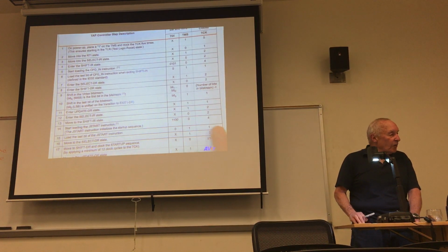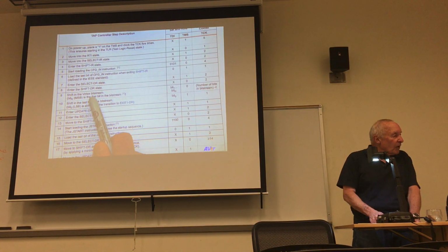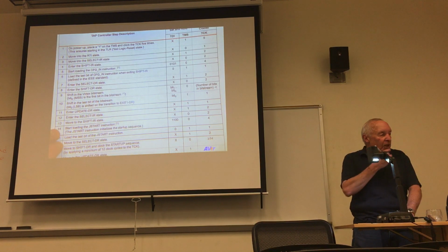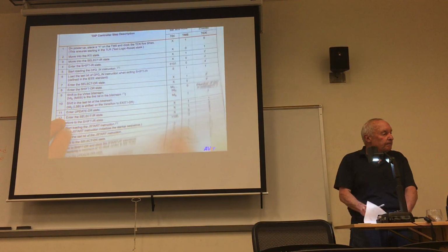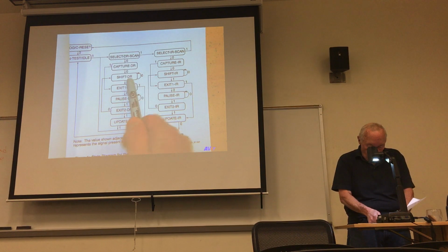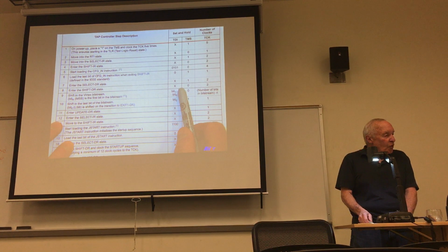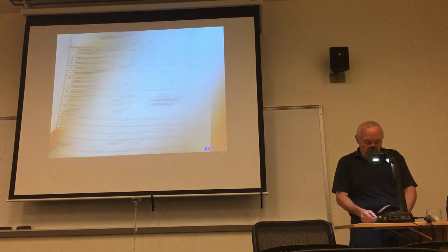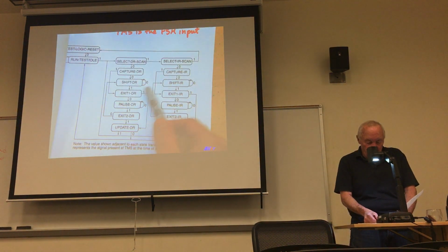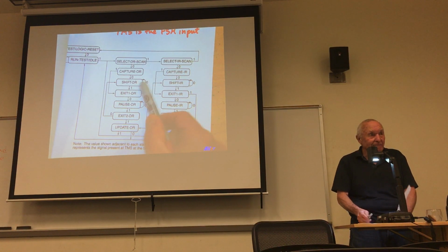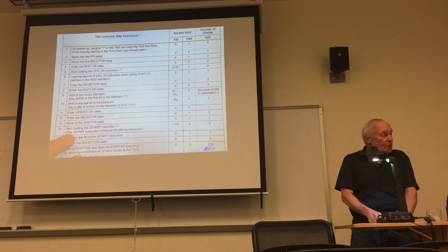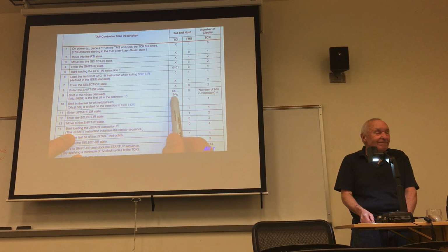Here's the key thing, is to go down to number 8, number 9. If I follow these steps, eventually I'm going to get into the shift DR state. That one. Test mode select is going to be 0. So on any succeeding clocks, I'm going to stay in that state. And notice what you're clocking in. The bits of the bit stream.